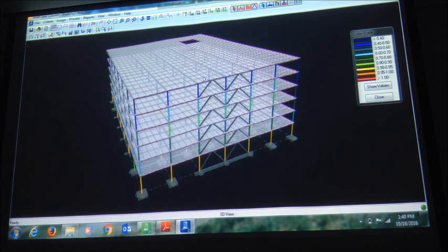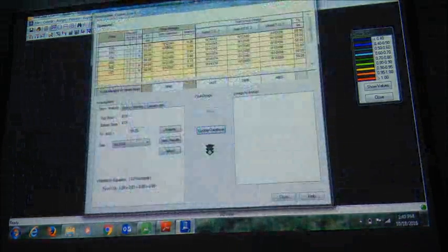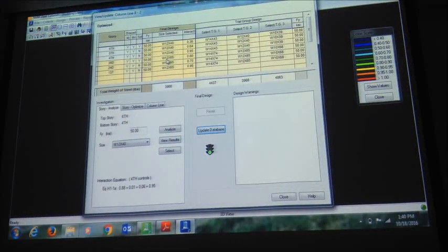That's the part I love in steel design. You don't have to wait too much. Okay, let's see the column. This gravity column, or maybe a bigger one, let's say this one. Column size 12 by 40 on the upper 3 floors. That's where the splicing comes into play. And lower 3 floors, 12 by 65.